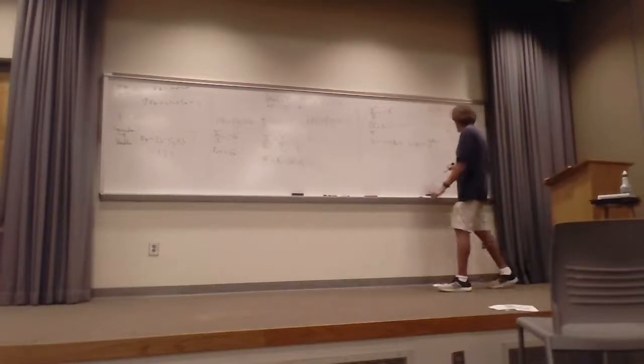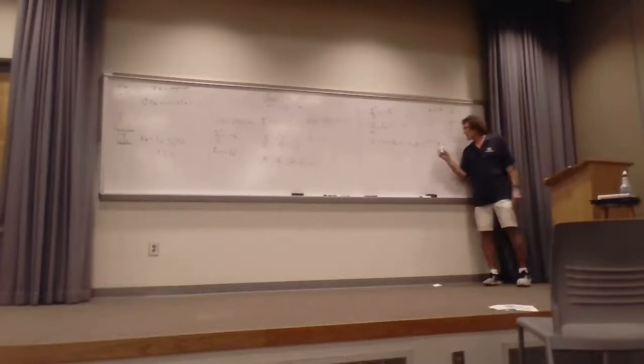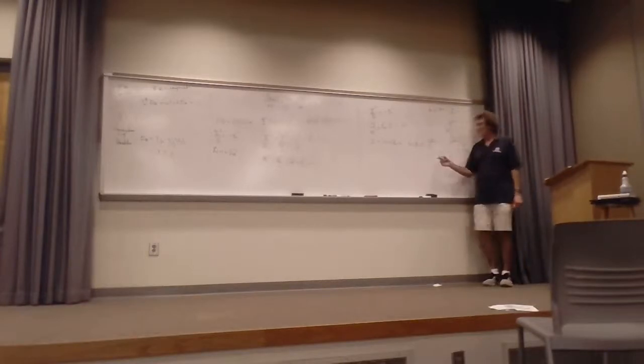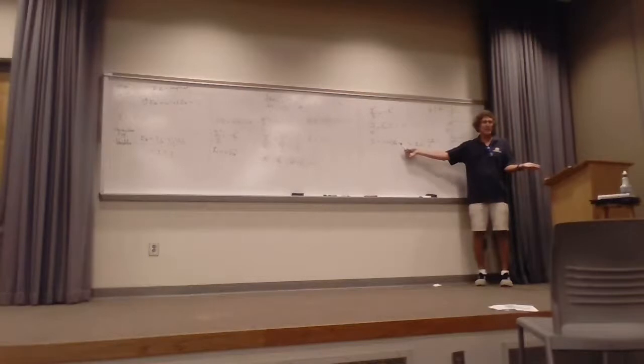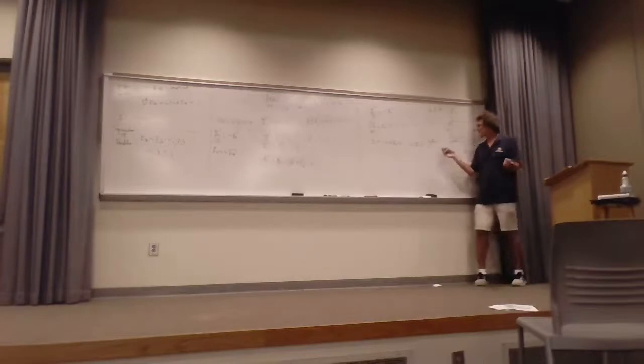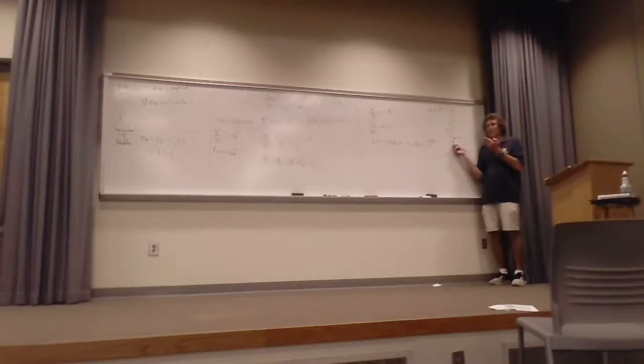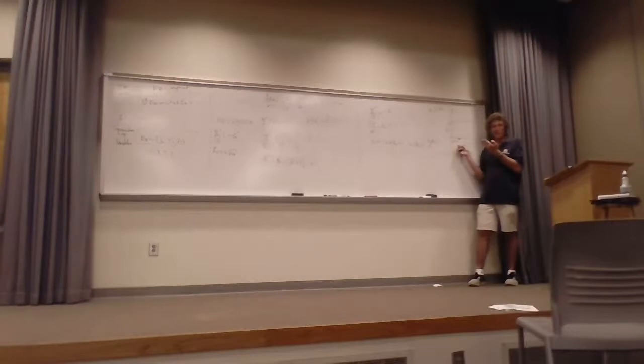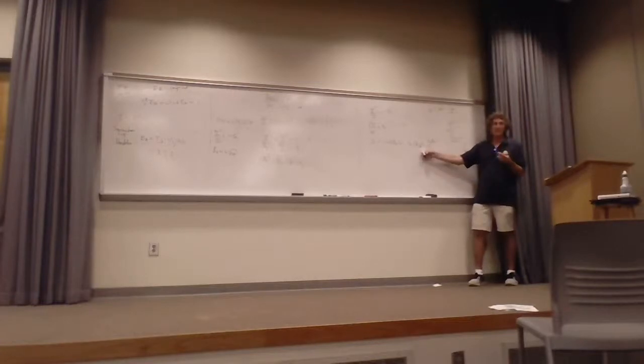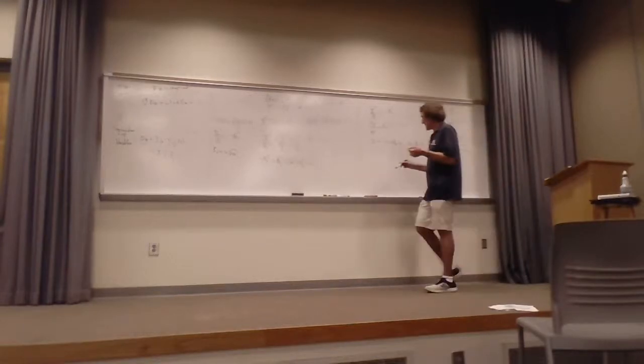And the only thing that'll work, if you look at this, if you have a cosine, because this is x equals 0 here, if you have a cosine of 0, it's 0, right? No, cosine of 0 is 1, isn't it? So when x is 0 here, regardless of the value of beta x, the cosine is 1, right? And if the E field varied as a cosine, it wouldn't go to 0 right here. But the sine would, wouldn't it? And likewise, this plus or minus j beta x times x, that always has a magnitude of 1. The phase changes.